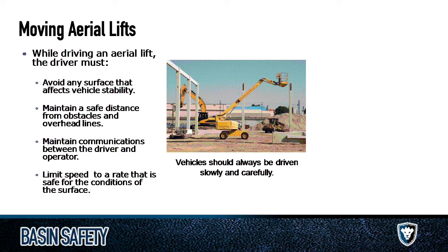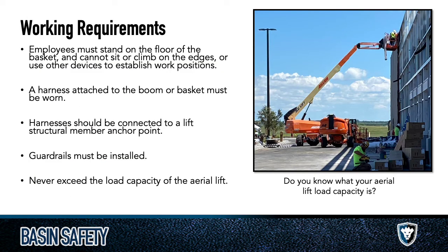I'm not saying you can't move it, but what you want to do is angle it at the right angle first, so you can articulate it or tilt the basket or whatever you have to do to get to where you're going. If your tires are not in the right spot and you need to move, get down to the equipment, move it, and then boom yourself back up. Don't do that from the air. It's a terrible idea. And don't have someone do it from the ground while you're in the air. Also a terrible idea. You want to be in control of that thing.